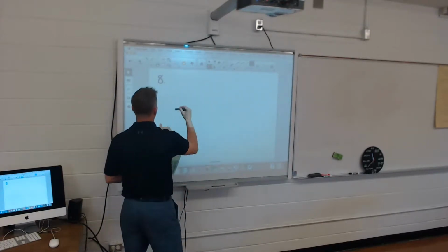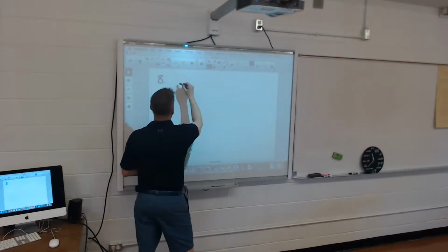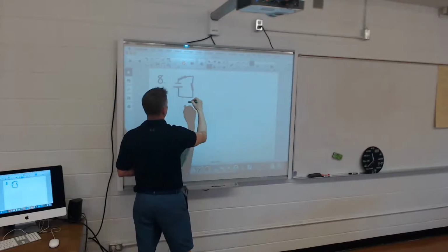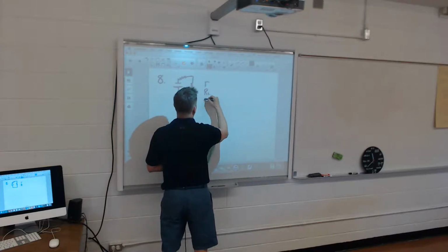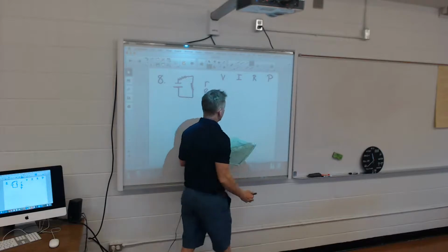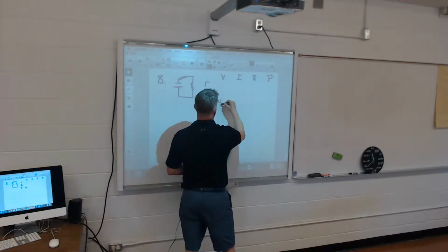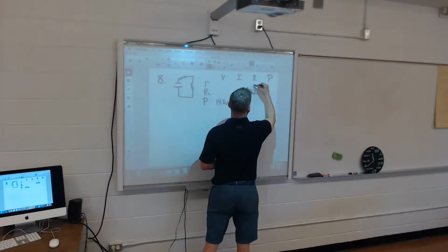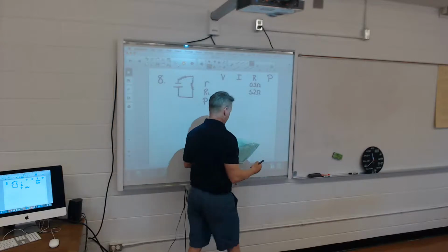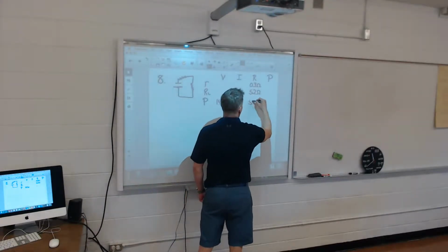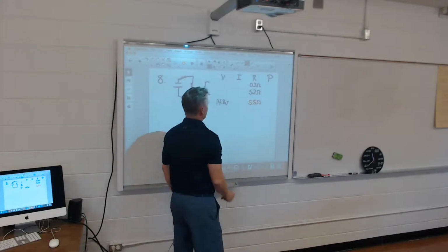Number 8. Okay. 14.8 volts. 5.2 ohms. 0.3 ohms. All right, so let's just fill it in and then we'll talk about the information. So first things first, this is 5.5 ohms. 14.8 divided by 5.5 gives me 2.691 amps.